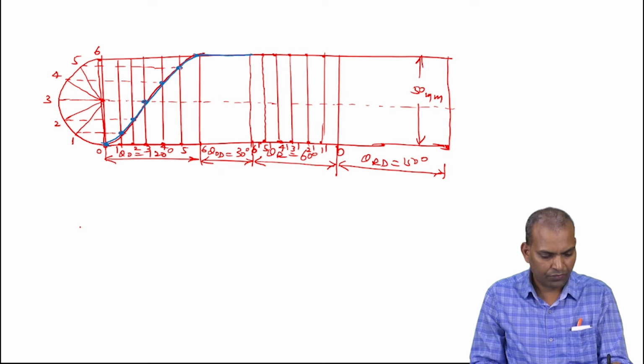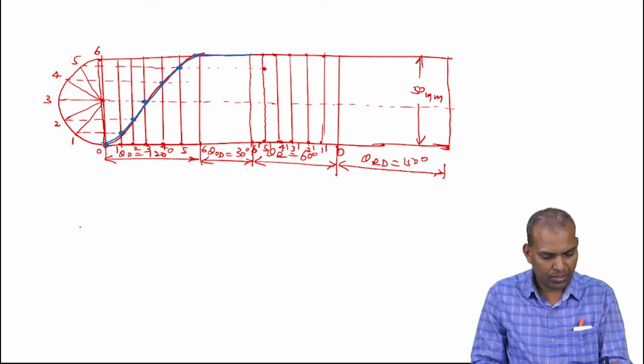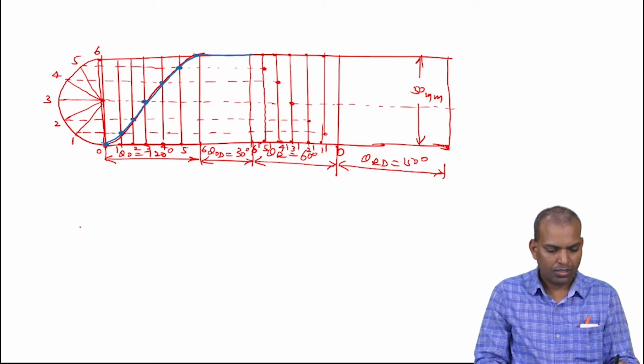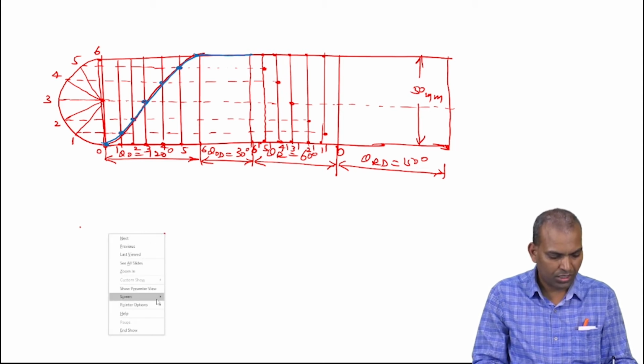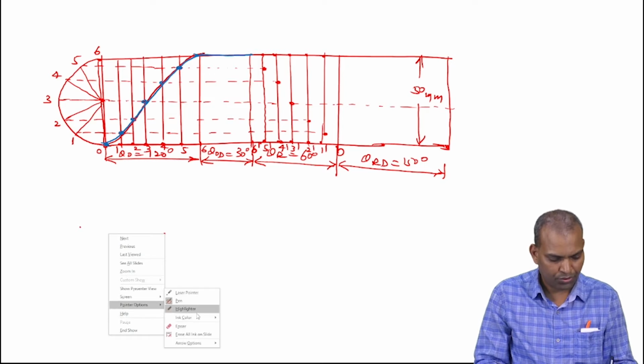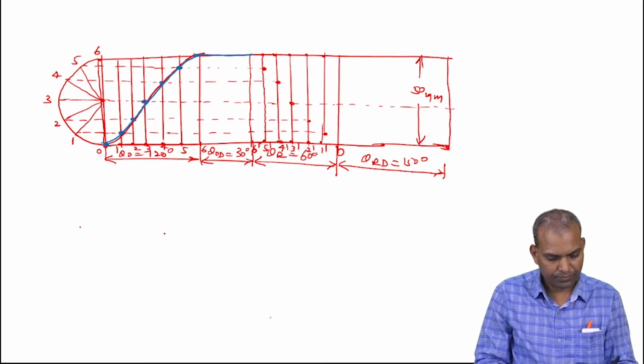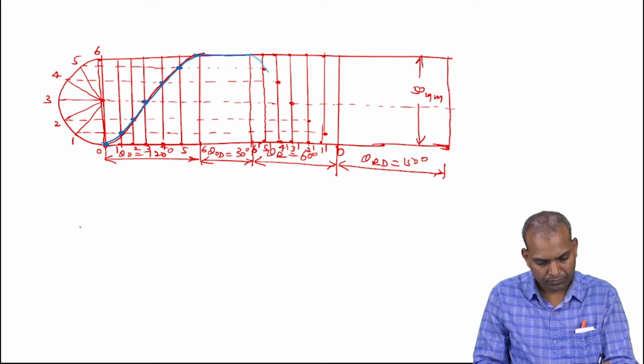So this 5 is intersecting with the 5. Draw a line with the 5 point. Similarly 4 horizontally, the 4th. It is 3. 2 with the 2 dash line, and 1 dash line. So by joining all these, again join a curve that gives the simple harmonic motion curve during the outstroke. A smooth curve comes.